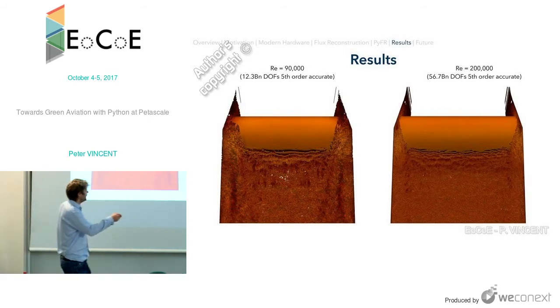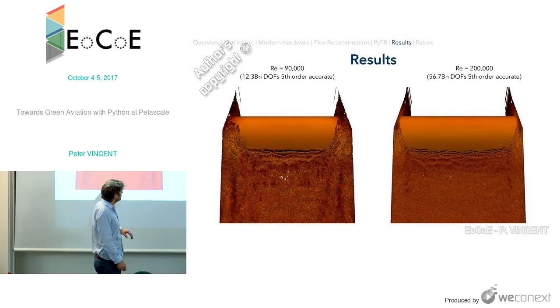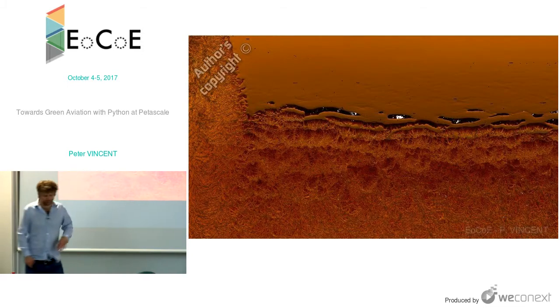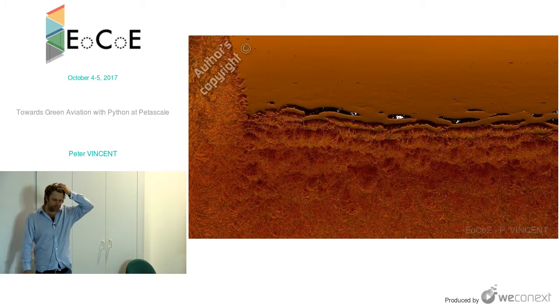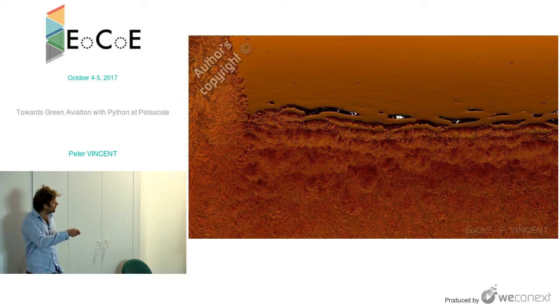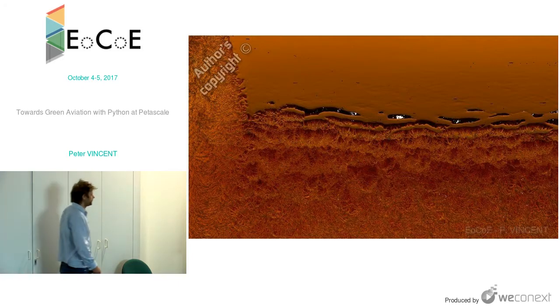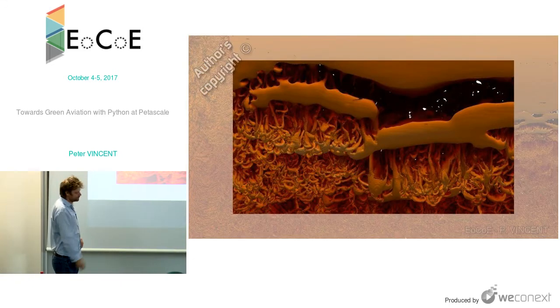The full blade at full span with end walls, and this particular configuration has end walls that are expanding, and there's lots of interesting physics there. You can see, so these simulations have actually higher resolution per blade than our previous simulations. So this has 56 billion degrees of freedom per blade. You can see all of the scales that we're resolving. You can zoom in and into these images, as indeed the slide does, that was convenient. So you can see all of these structures.